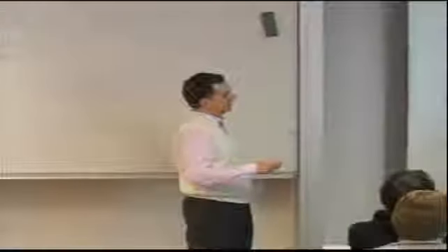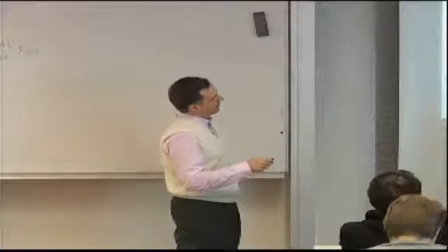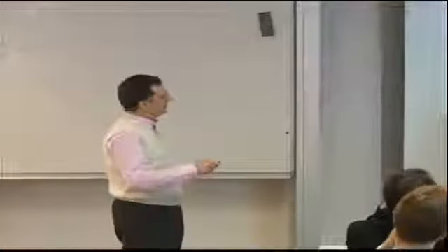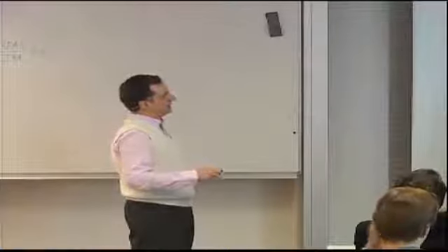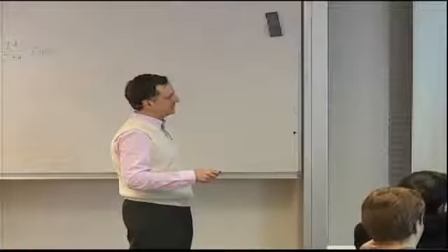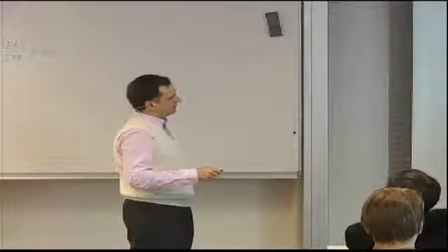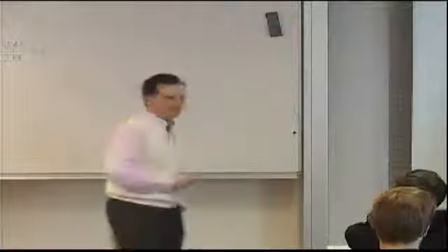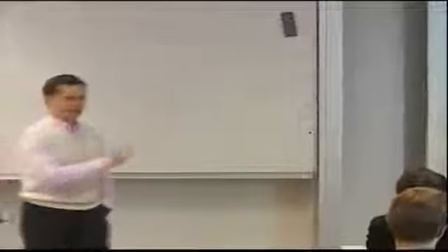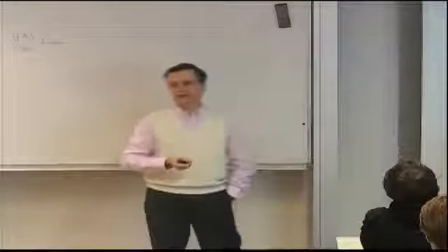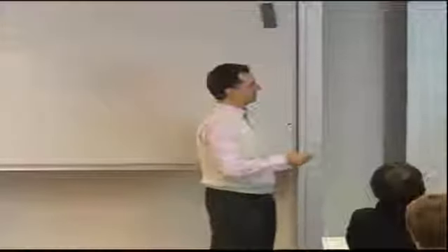So crippling would occur for the first one at this load, and my applied is 40. So 40 is less than that, so I'm in good shape. And so on: if I take the ratios, anytime the ratio is smaller than 1, I'm in good shape. If it's greater than 1, it means my applied stress is much larger than the capability of the structure in crippling. So this clearly says your design is miserable because the skin fails, and it fails by a lot because this is a pretty big ratio.